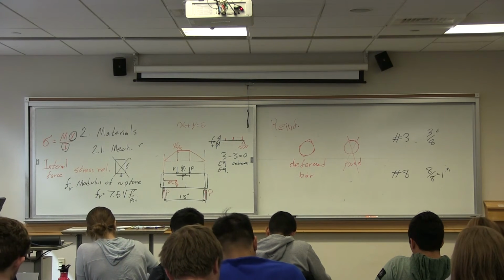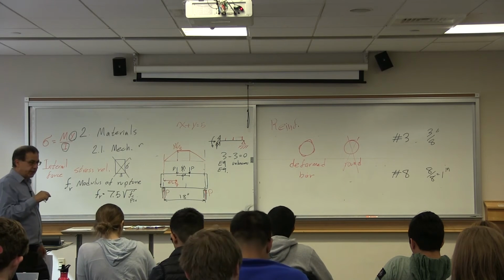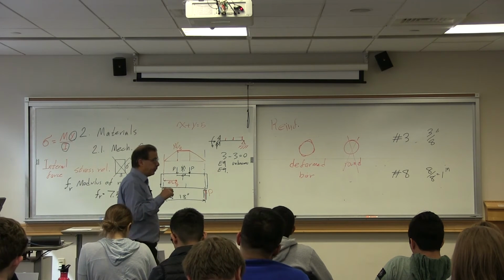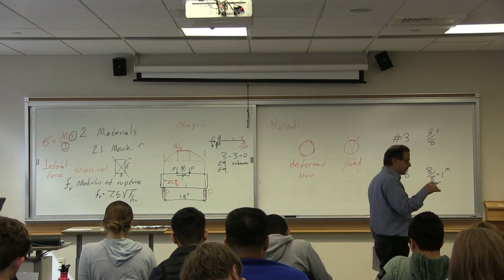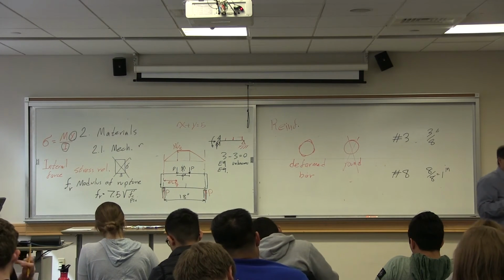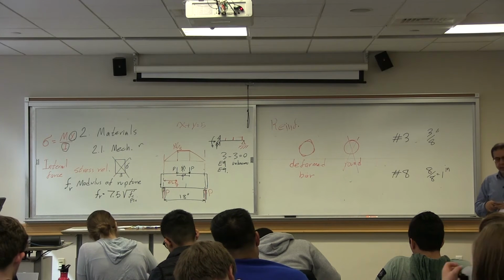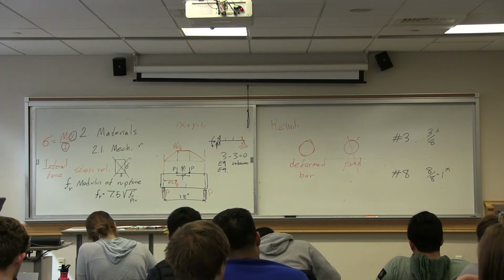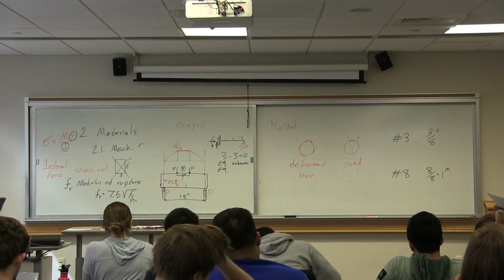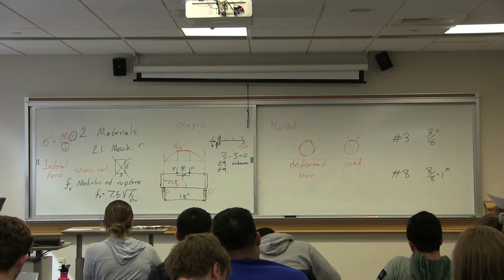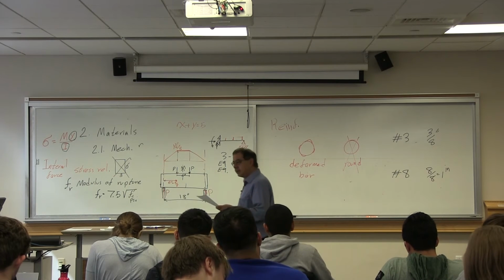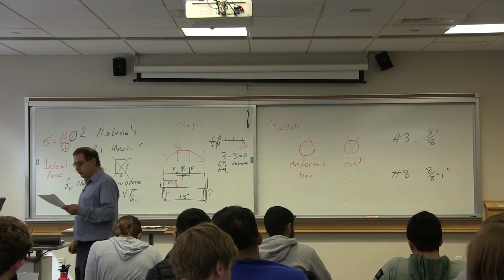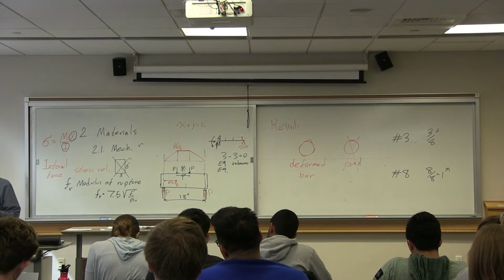However, the diameter of number 9 bar is not exactly 9 divided by 8. Starting with number 9, there is a slight variation, and the reason is to have a better number for area. For instance, 9 divided by 8 is 1.125, right?